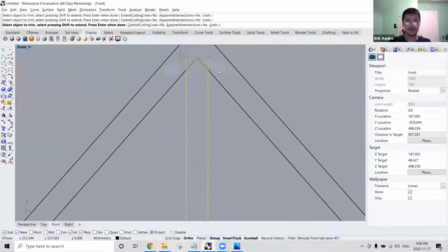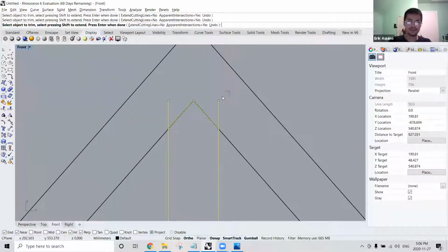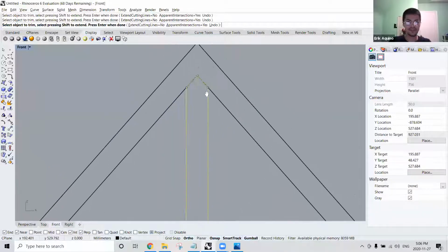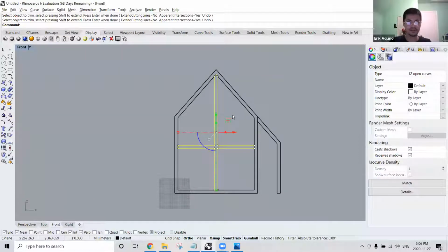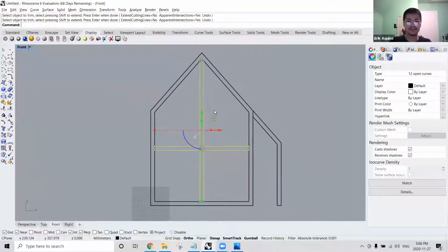I'm doing my window selection, so I'm dragging right to left in this case. Hit enter when you're all done, and do join because we love a closed curve that's all connected.